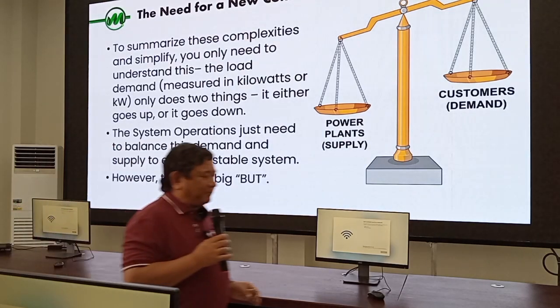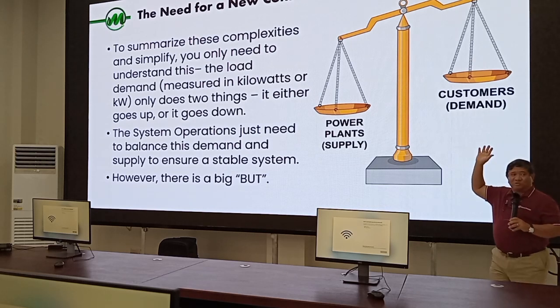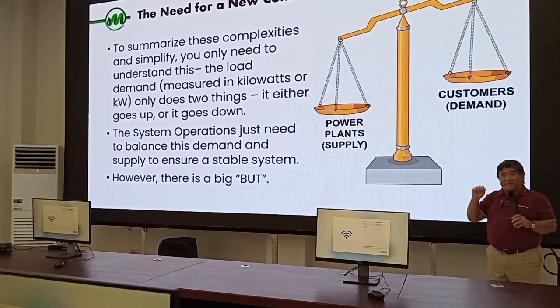That one is very important when we say stable system because ang demand ng customers is always stable. When I say always stable, we want the voltage in our homes, in our offices, in our businesses to be within the 220 volts plus or minus 5% plus the frequency of 60 hertz.